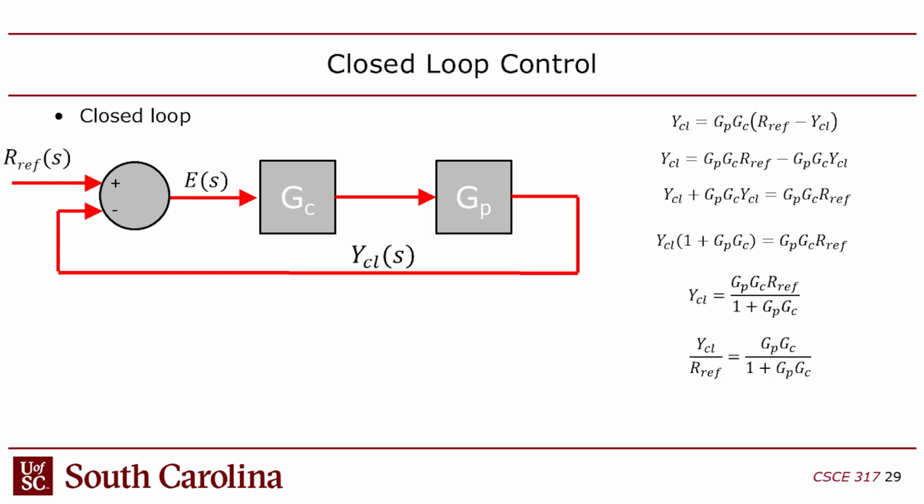So I mentioned that when you convolve, you take two transfer functions and you mash them together. That creates the open loop transfer function, right? The problem is no one uses open loops except dummy toaster manufacturers and dryer manufacturers. Most control systems are feedback control, closed loop systems. So how does that work? How do you calculate the transfer function? Well, it turns out it's just algebra. It all boils down to simple algebra, at least because we're keeping everything simple here.